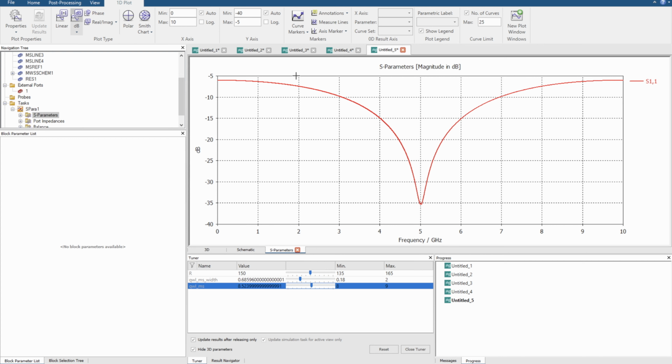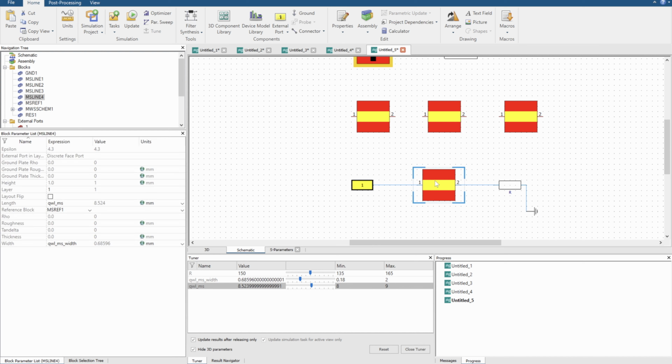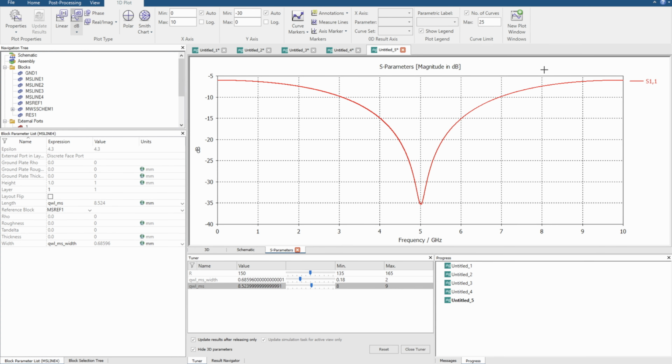There's one very important thing that I just did here. Let's say in a hypothetical sense, I didn't know what the load impedance was of, let's say, an antenna, or I didn't know what the input impedance is to a certain block. What I've then done is I've tuned a match condition.